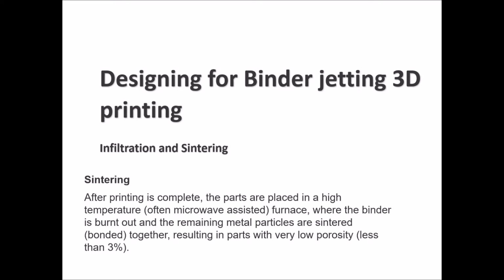Usually these parts could be functional parts, and so our goal is to reduce the porosity. The lower the porosity, the stronger the material. The higher the porosity, it means there are more holes in the microstructure of the part, which means the part is weaker in general terms.